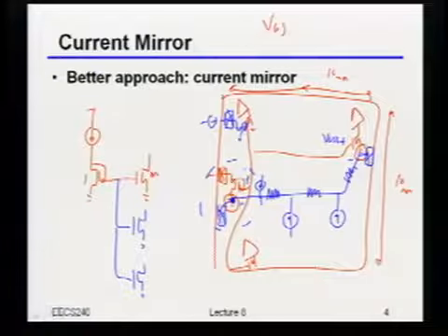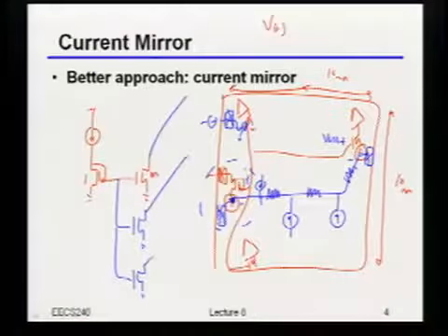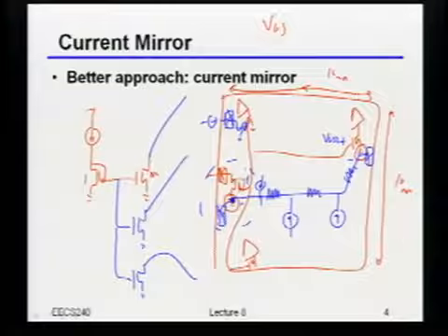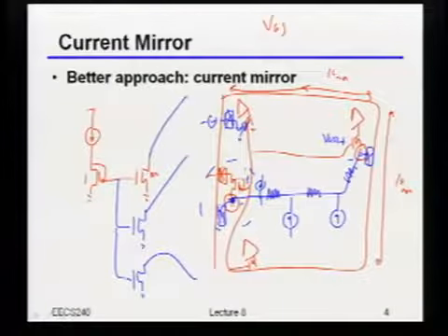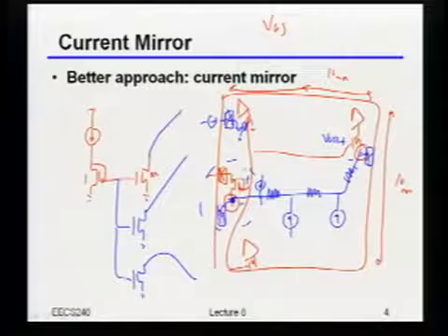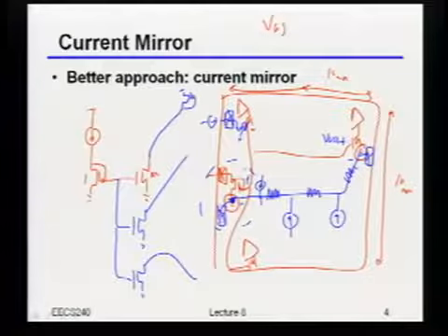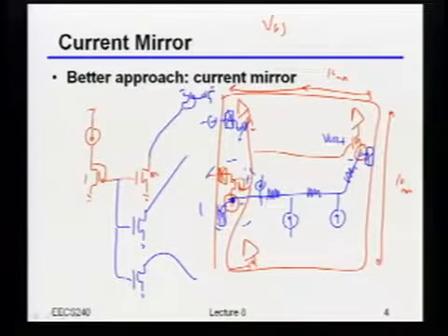And then I would route those currents out. Once I've routed those currents out, at the point where I actually want to use it, and let me move this wire a little bit so it's easier to see, I can just mirror it back into another current mirror as if I had something coming from outside the chip.